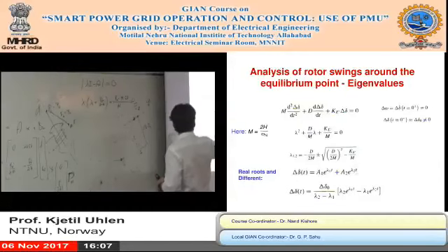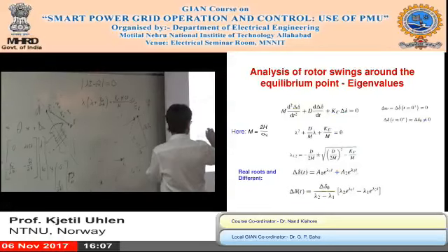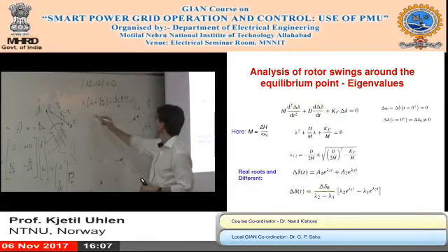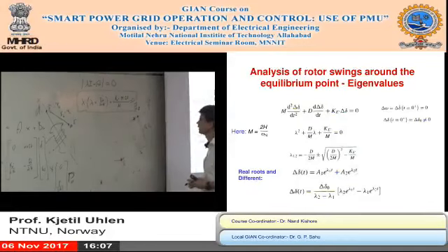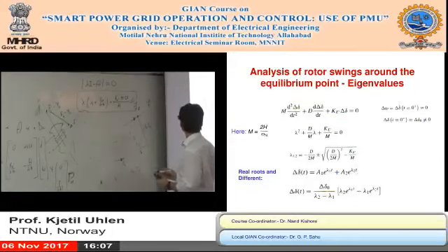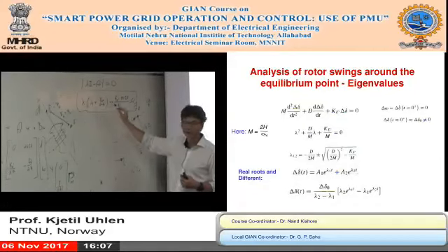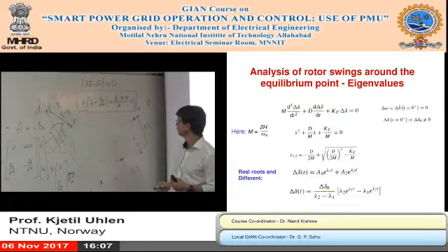It's the same as this one, but that one is a little bit, to me it's not clear if this is per unit or not. But with the characteristic equation like this, it's definitely in per unit. And it's the inertia constant that you're used to in seconds. That is why I put it on this form.